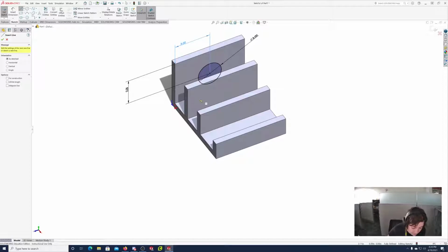The directions say select the line command and sketch the 3 lines as shown below. Snap to the hidden edge of the model when it lights up. So the hidden edge is, you'll see when I hover over this line here, it turns orange. We can snap our line to that line so that when we draw it, it lands right on it.